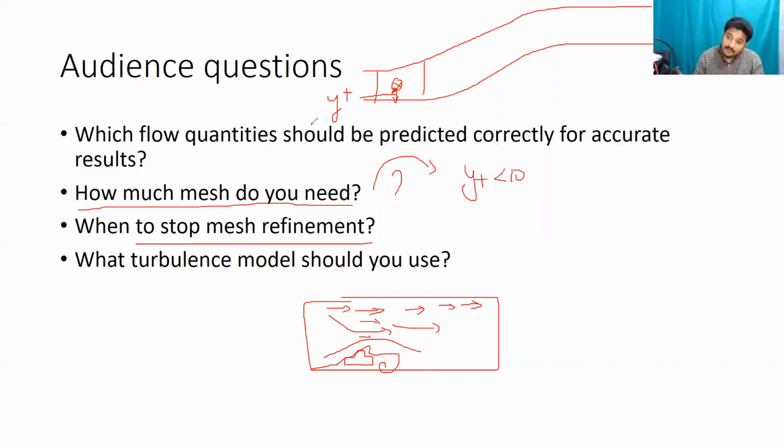It's always laminar. So when you refine the mesh extremely, you basically get inside the boundary layer. Your mesh is so small that you're resolving the boundary layer. But when you're resolving the boundary layer, you're still solving the K and epsilon equations, which are part of the turbulence model. And solving those equations is wrong because they will give you incorrect values for the shear stress, which will give you an incorrect value for drag coefficient. So Nikhil, did you understand my explanation?